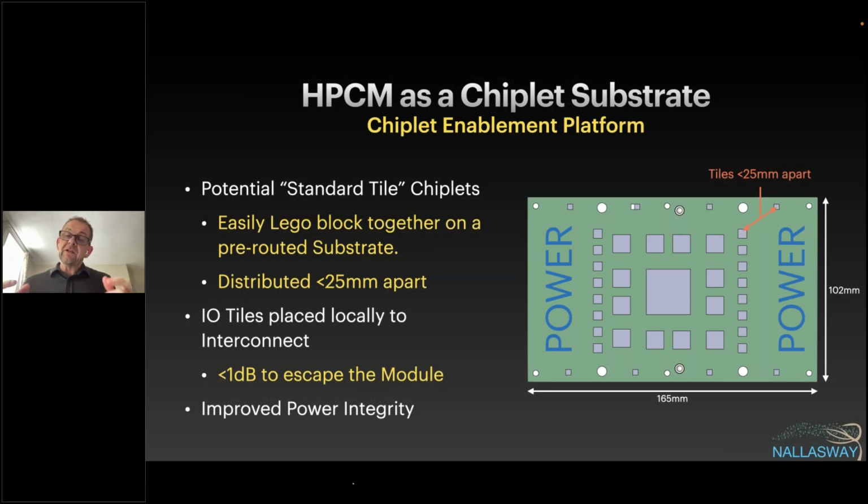Okay. I was thinking that you could, and obviously there's lots of different ways of doing the advanced stuff like the EMIB, etc. But if you had a standard CoWoS, you could potentially have a CoWoS die with all of the advanced chiplets on top, and then you could mount this as the package substrate instead of putting a CoWoS into a normal package. So you could potentially do that.